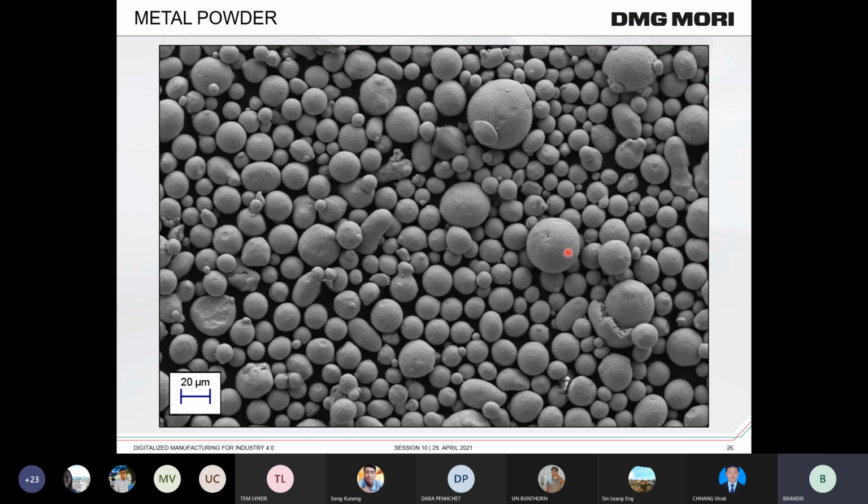And normally, if we melt it with the laser, the effect is that in the powder there is air between the several particles, and if you melt it, there's no air inside, and so the density of the melted area is higher than the density of the powder. To avoid problems, we optimize the powder so that there's a variation of small and bigger particles.